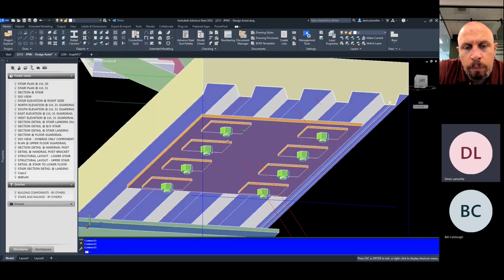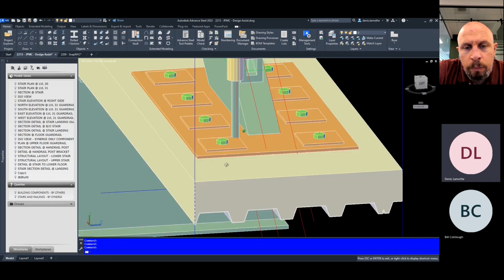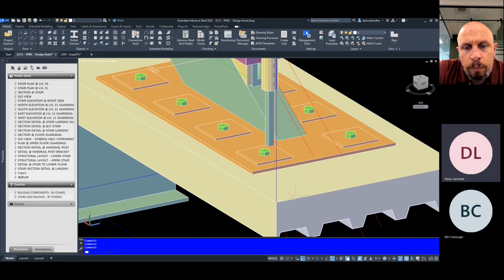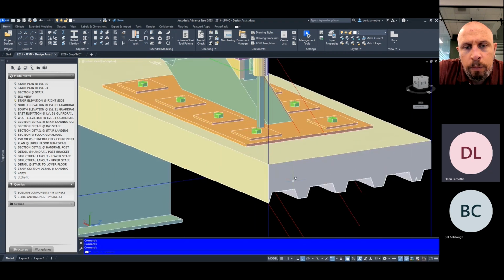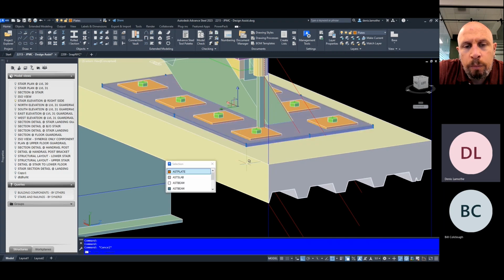If we had questions or issues about possible rebar in a slab, we could oversize the holes in the slab and also in the base plate, and then these plate washers would be a tight fit hole with a bolt, and wherever the washer and the bolt ended up being, to clear any members in the slab, we would just come around after the fact and weld the plate washer to the base plate, and secure everything together that way.